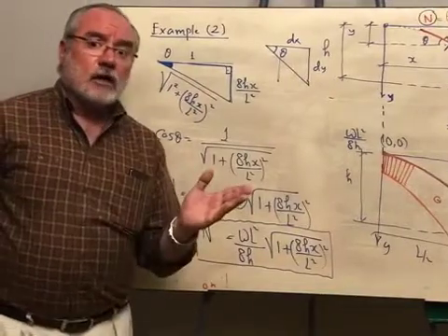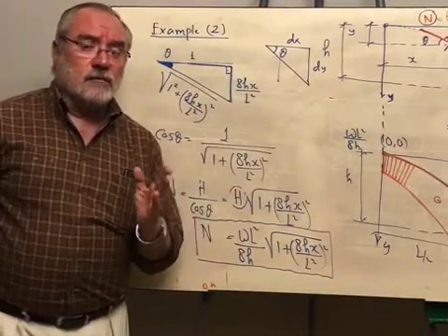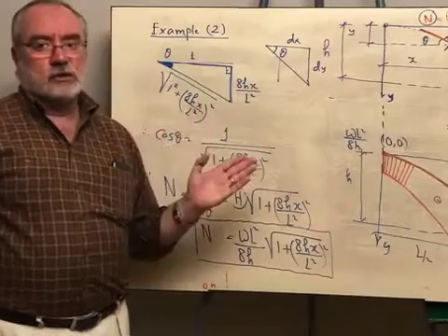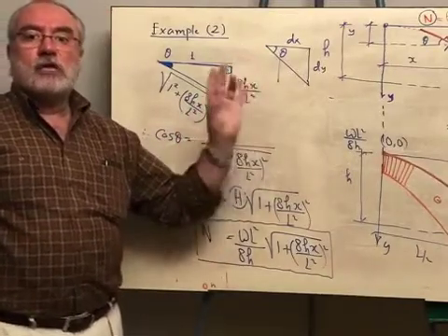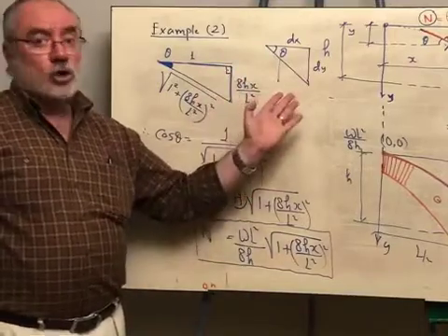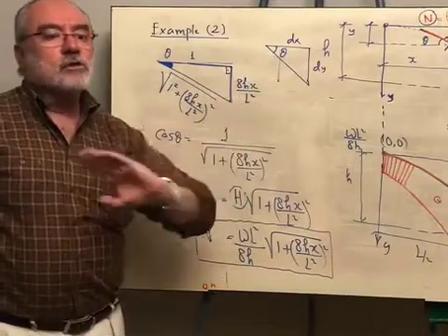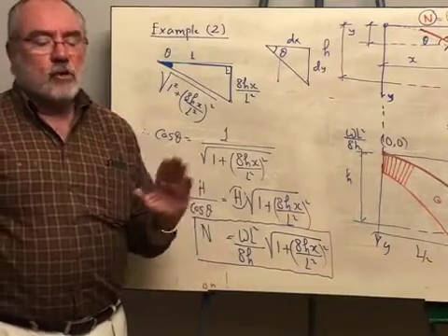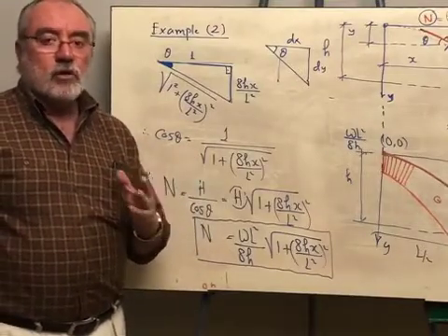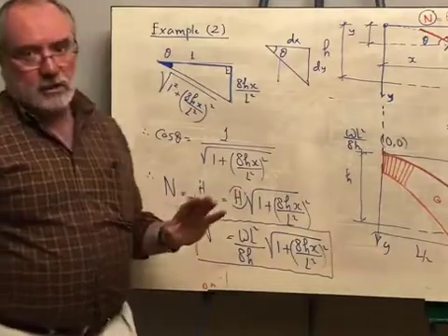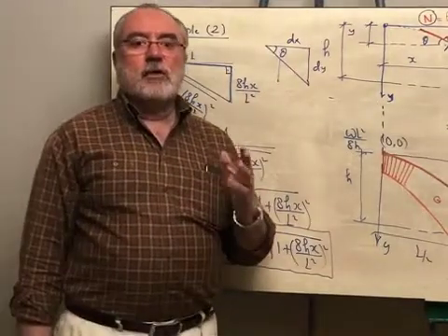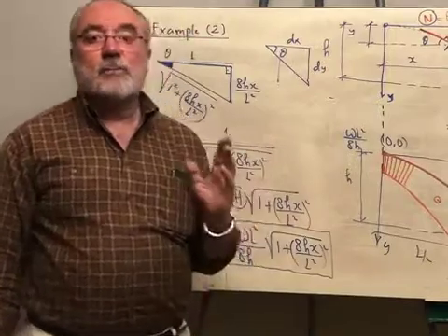The other type of arches that we can solve together in this course is the three hinged arches. For the three hinged arches, you will have to calculate the normal force, the shear force, and the bending moment because it is no longer funicular, and we will use the principles of superposition or equilibrium that we learned throughout the course. There is nothing new about that. The other lecture will be on three hinged parabolic arches.